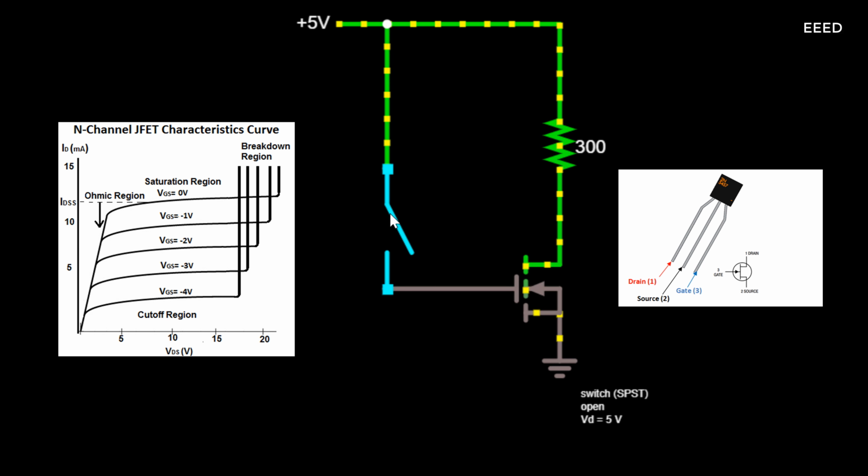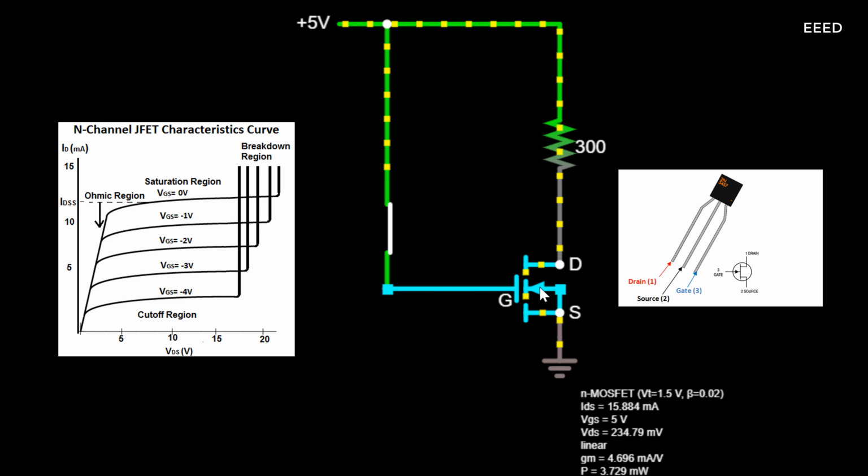The transistor is in its fully conductive state and is in maximum operation when the voltage at the gate terminal is 0V. As we increase the amount of negative voltage the gate terminal receives, the transistor becomes less conductive. Once the negative voltage reaches a certain threshold, the N-Channel JFET circuit stops conducting altogether across the drain source terminal.